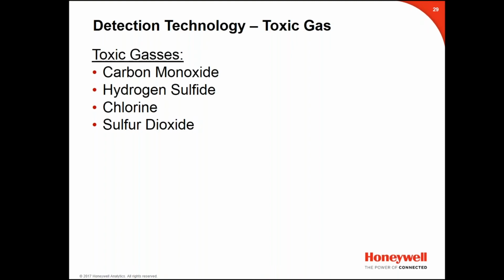Additionally, electrochemical cells are used for oxygen depletion or oxygen enrichment applications. Electrochemical cells are compact, require very little power, exhibit excellent linearity and repeatability, and generally have a long lifespan, typically 1 to 3 years. Commercial designs of electrochemical cells are numerous, but share many common features. Active gas diffusion electrodes are immersed in a common electrolyte, frequently a concentrated aqueous acid or salt solution. And this creates efficient conduction of ions between the working and the counter electrodes.